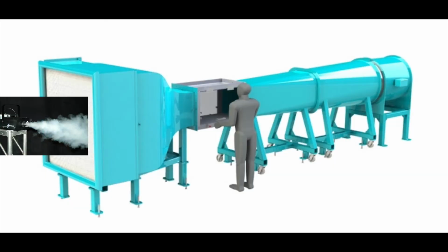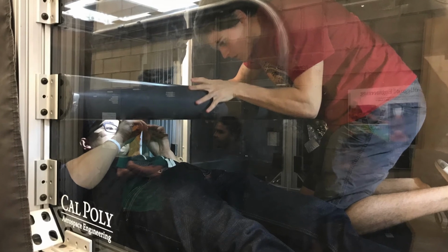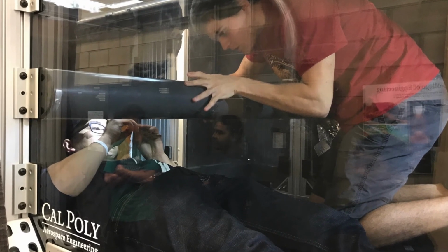Initial pressure and temperature were recorded before the start of the experiment in order to calculate the initial air density. Next, the cylinder was checked for correct dimensions and that it was properly positioned in the tunnel. Floodlights and a laser were used to illuminate the smoke near the cylinder, revealing vortices as they were shed. A phone camera was used to record the flow of the smoke above and below the cylinder, and to capture slow-motion video of vortex shedding across the cylinder.